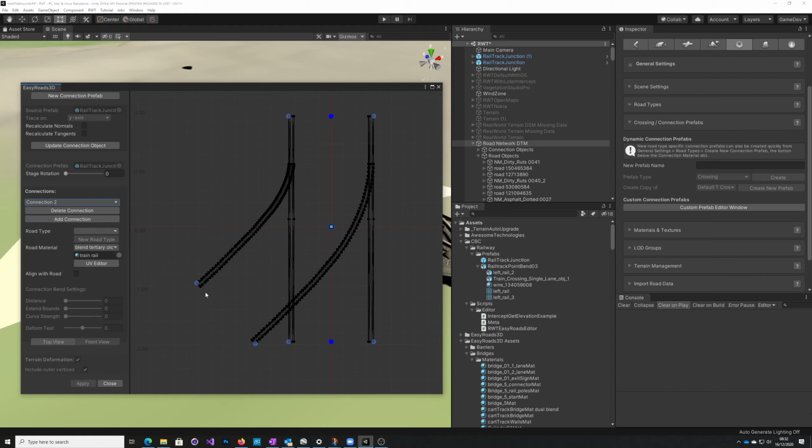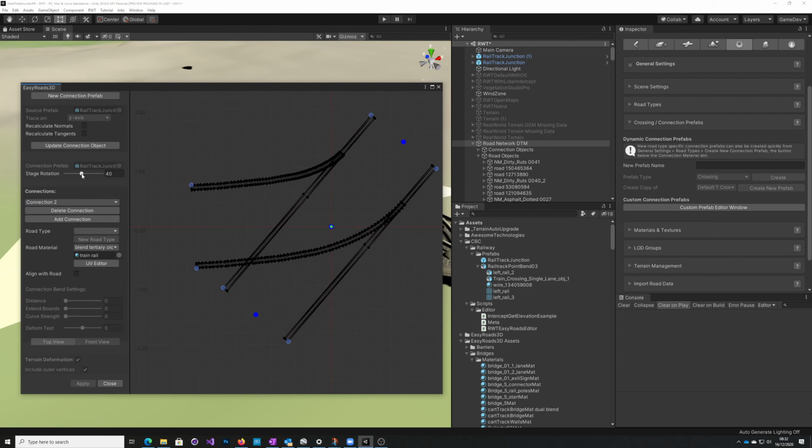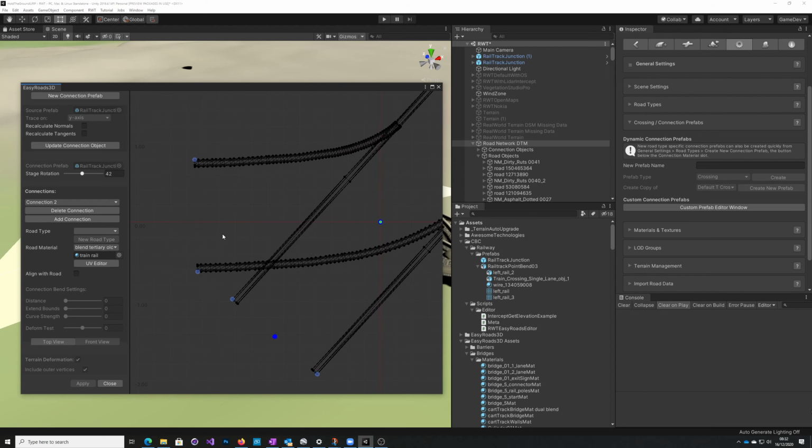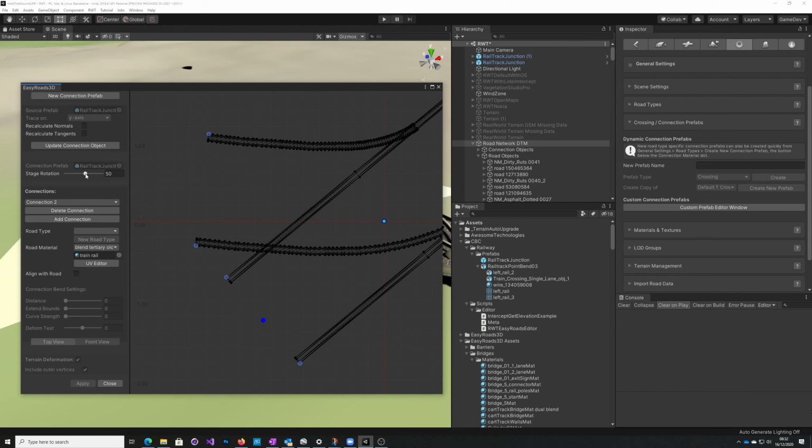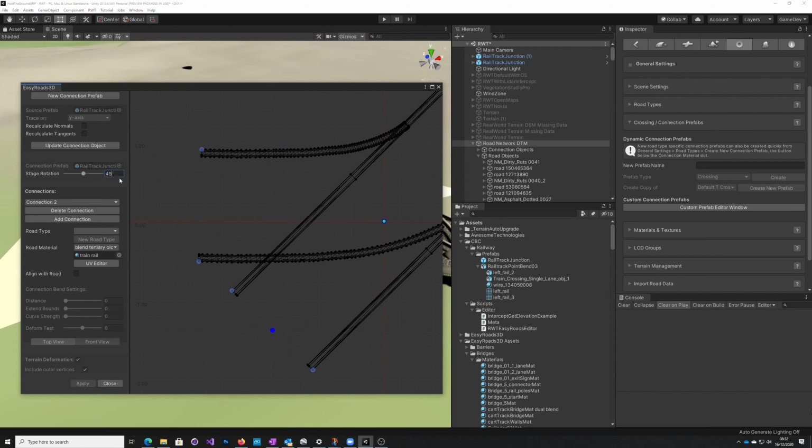Now, I need to be able to highlight these. And as you can see, my designer's given me the curve, and it's got lots of vertices on it to create that curve shape. So what I need to do is rotate this around, zoom in a little bit, and I guess 45 is going to be the point, and then shift and make the selection, missed, shift, make the selection.